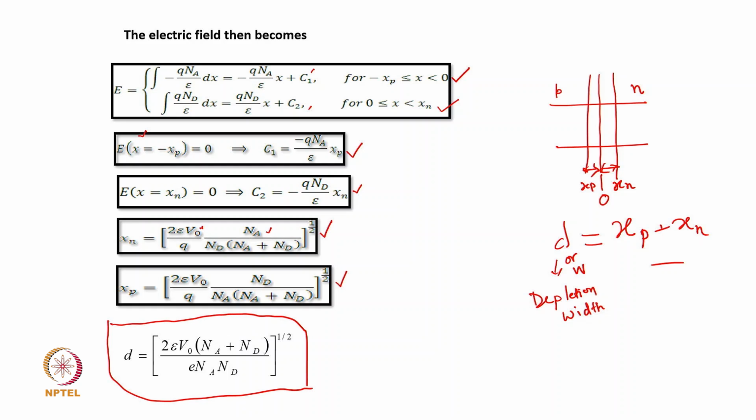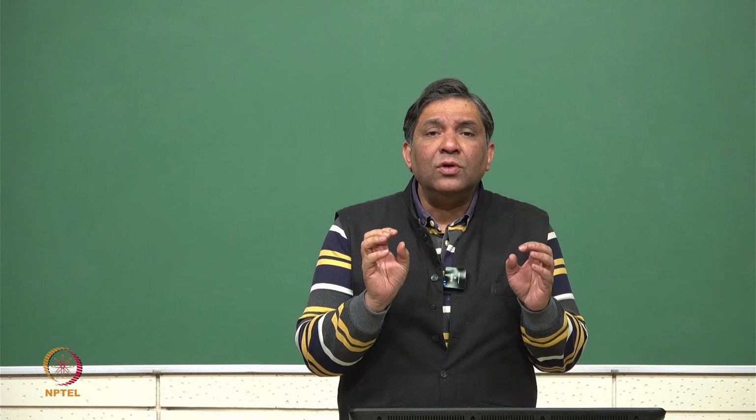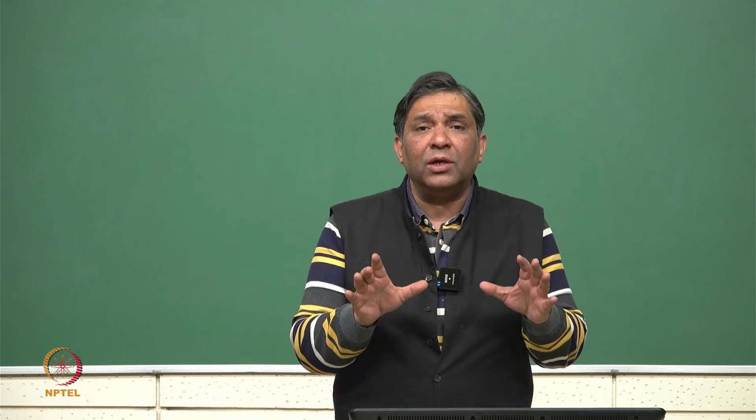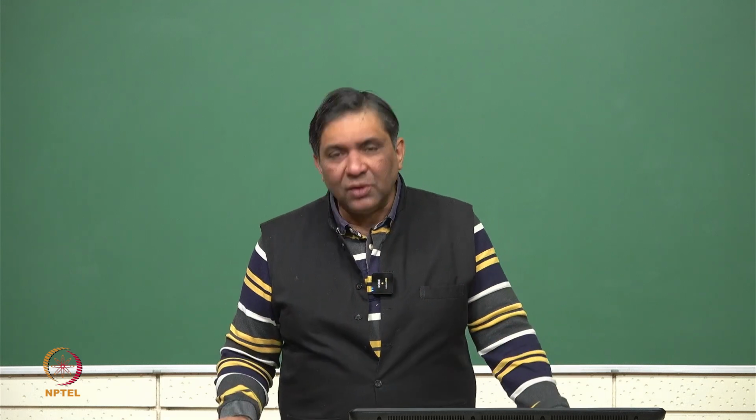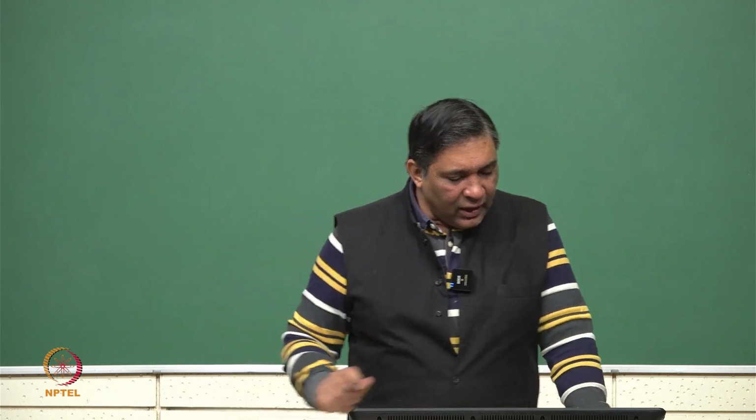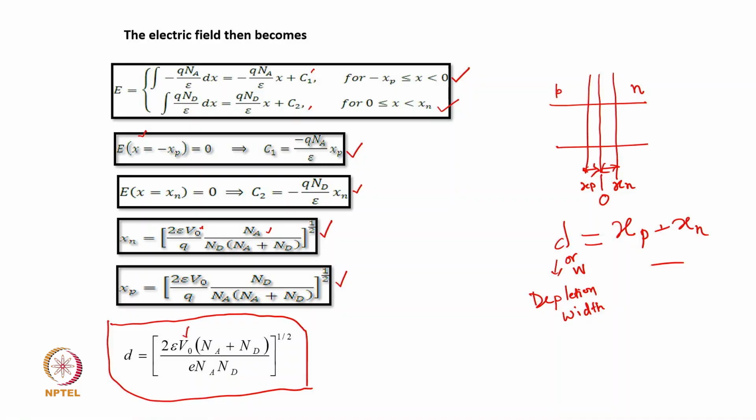Whenever we start with a solar cell with a particular material, we have to look at what the depletion depth is, because the photons are basically absorbed in that particular region, which is the effective region of the solar cell. It depends on the potential height V naught, which is generated across the p n junction.